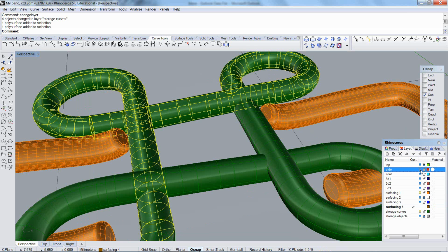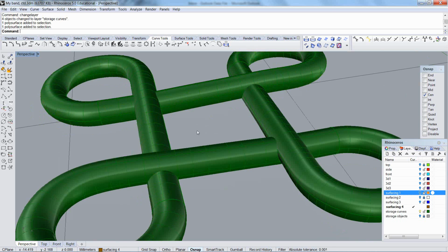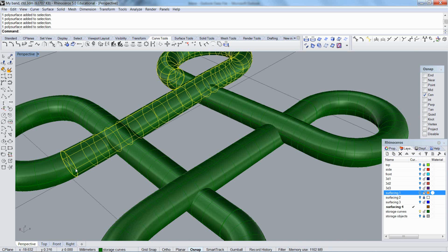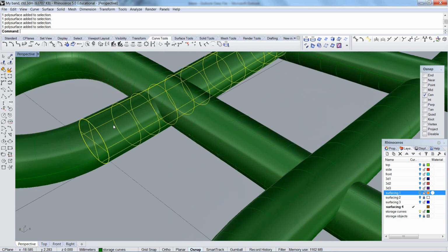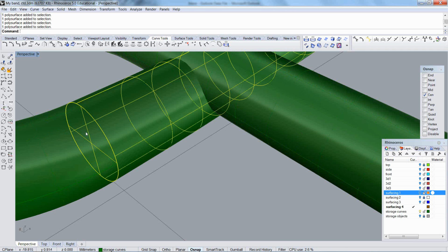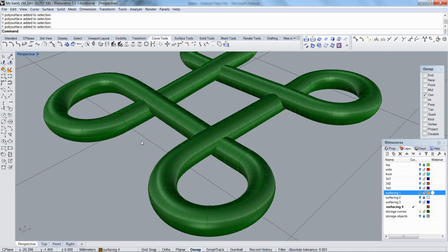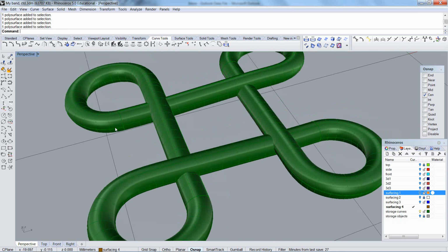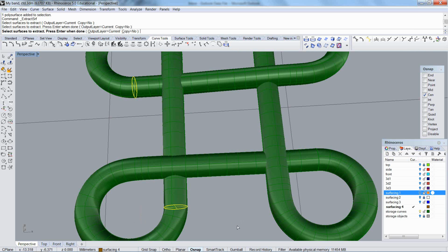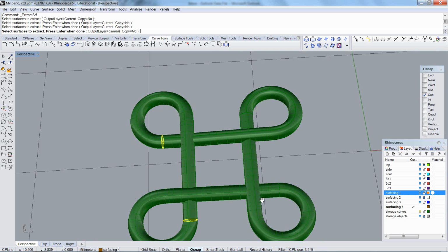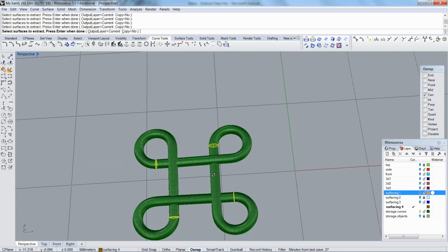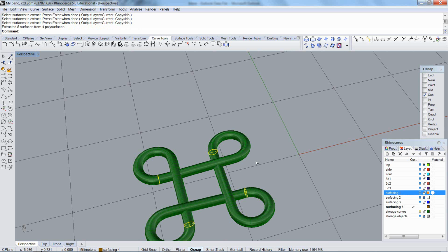Trying to get down to where I just have this layer to look at. Okay, so if I Boolean this right now, it's likely going to fail because I have a coincidental surface with those two caps. You can see cap there, cap there, cap there, cap there. And if I remove the caps, which I'll do right now, extracted those surfaces, delete them.